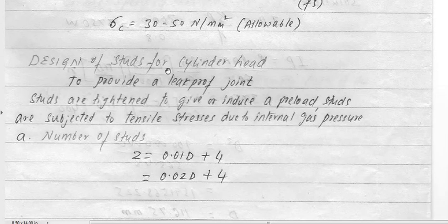Now the design of studs for the cylinder head. Why are studs used? To provide a leak-proof joint between the cylinder and the cylinder head. The studs are tightened to induce a preload, and the studs are subjected to tensile stress due to the internal gas pressure.